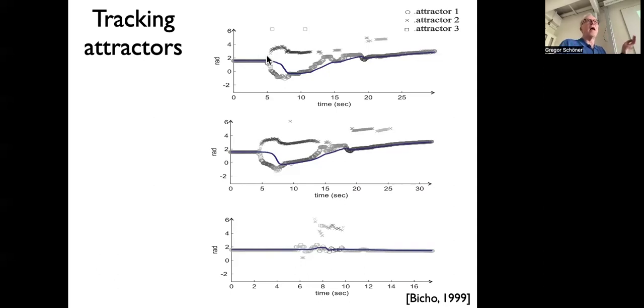I should say, having the data on the robot, you're able to compute the fixed point, right? Just post hoc from the equations, and that's what is done here. And so you see there the split. There are two attractors now outside. The solid line is the actual heading direction the vehicle takes. There is a repeller here in the middle that's not shown, that one could actually also compute by inverting time.